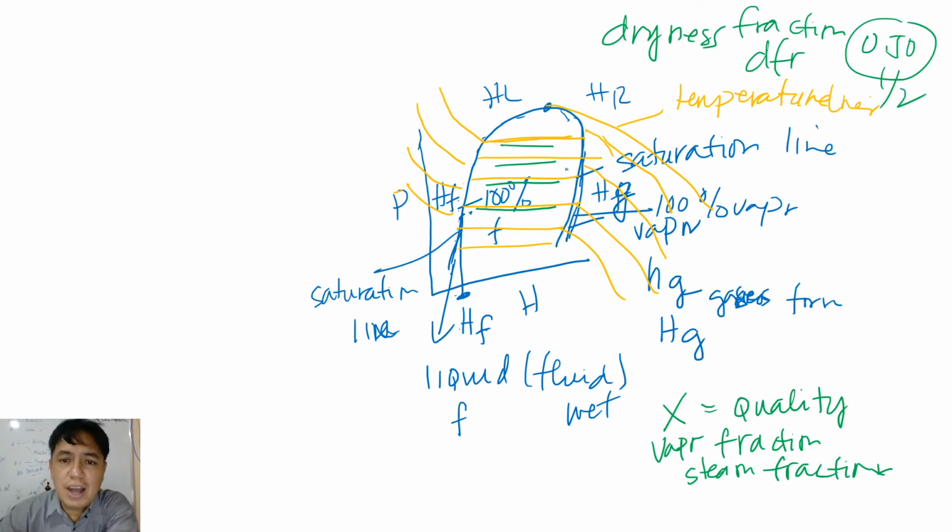So there is a fraction or quality of dryness in between the fluid and the gas. That's why there's a so-called X, meaning this is 100% fluid, this is 100% vapor. In between, there is this fraction, meaning if half is 50%, maybe 40, 30, 10, this is 90, 95, 98. Yeah, so if you are near the saturated vapor line, maybe you are 99 or 98, right? 98% or 99. When you reach this line, let me mark this off.